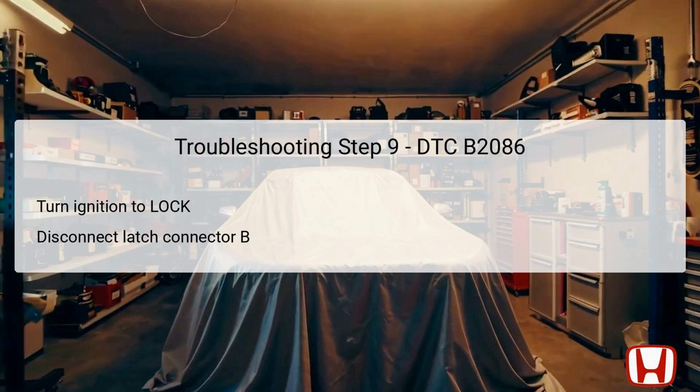Disconnecting the latch also lets you analyze whether the switch and wiring are functioning properly without interference from the control unit. Proper disconnection is essential to prevent damage to electronic components.